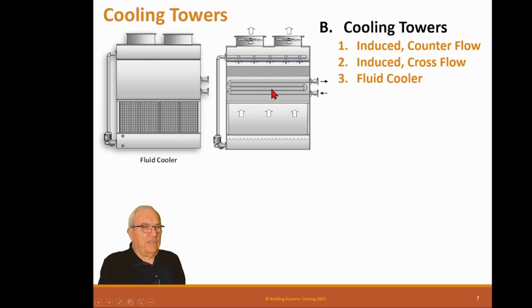But these have a problem in that you have a very small bunch of water. You may have down to 200 gallons, not much, in a fluid cooler, which means when things go awry, it can go fast. In a regular cooling tower, you may have 1,000 gallons or 10,000 gallons of water moving in the condenser barrel, so it changes slowly. These can change very, very quickly, and so sometimes the chemical treatment systems are not real robust on these, and so you can get some chemical treatment problems, which then can negate this tower. We've seen these last 7 or 8 years, and they are expensive.